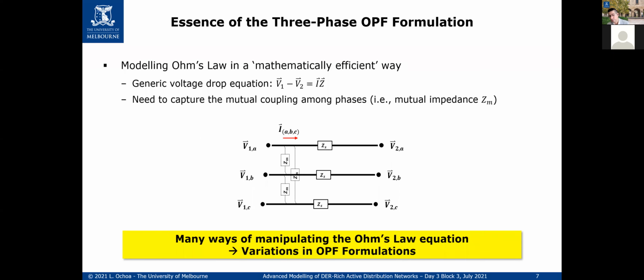And in some cases, you have single phase customers, you have parts of the network that are just taking one phase, the other. You can argue, like, Nando, but in reality, we have the neutral. Where's your neutral? Nando, where is the ground? We have neutral and ground. So yes, actually, in reality, if you want to be very, very precise, you should be modeling explicitly the neutral. You should be modeling explicitly the ground, all right? And actually, as a matter of fact, you should be modeling as well the grounding of the neutral, in the different points. But it gets to a point where the information is just not existent. And the benefits from having that sort of detail of the modeling is not that great. It might be important in certain circumstances. I'm not denying that. But it's about finding a trade-off.